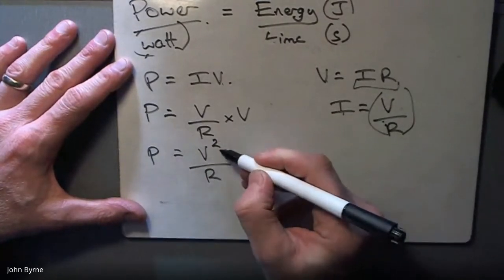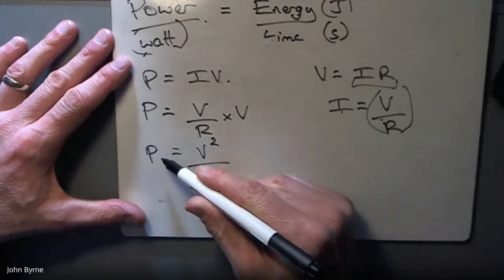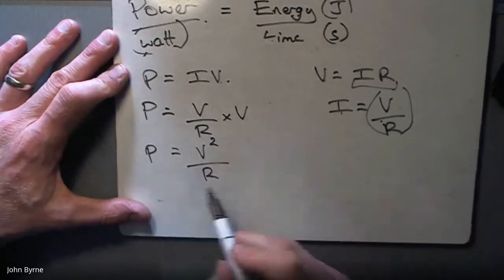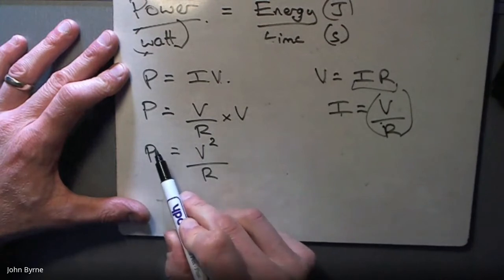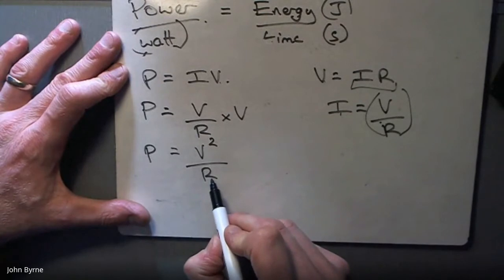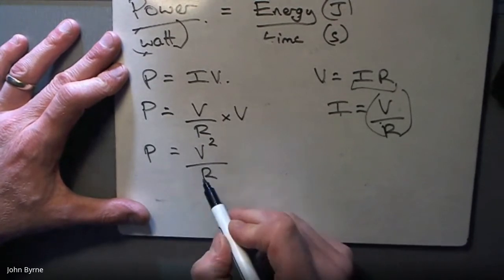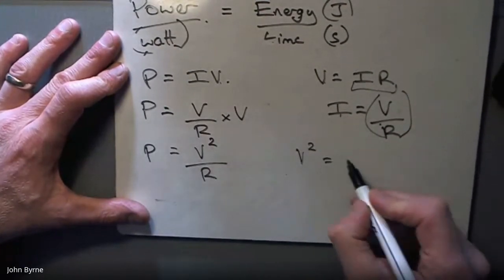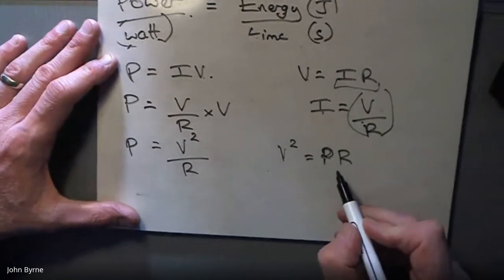And so you know the potential difference. We square it, divided by the resistance in ohms. That tells us the power dissipated in that circuit. And again, the most probably complicated one is if you want to find out what V is. Imagine you're told the power and the resistance. How do we work out V? Well, first of all, we multiply both sides by R. That would come up here and come up here. It would cancel on this side, leaving V squared on its own. But we still have to multiply. There we go, so power times resistance.